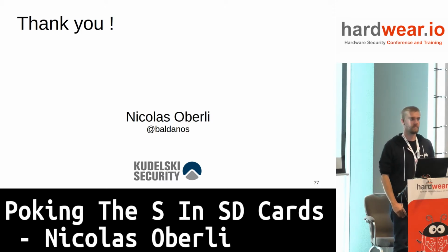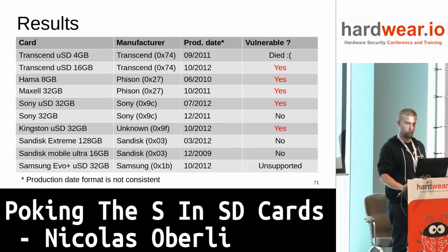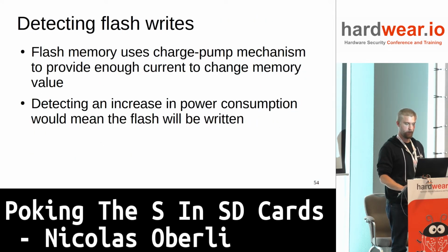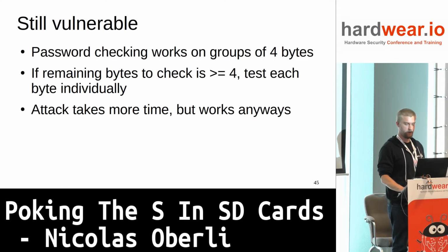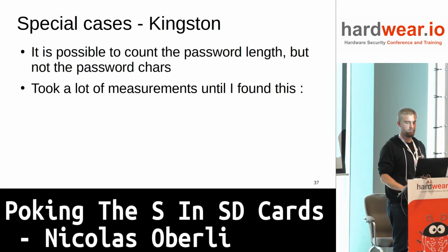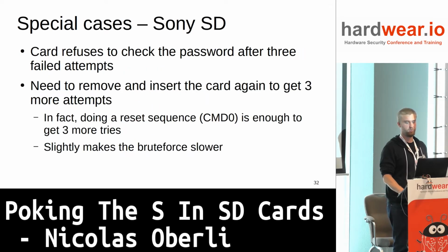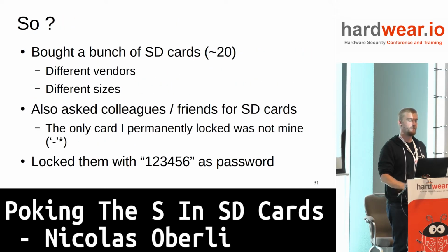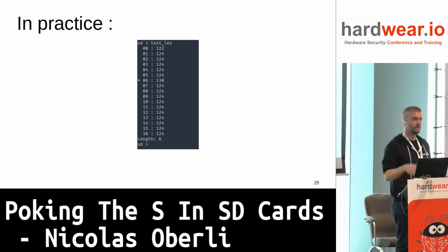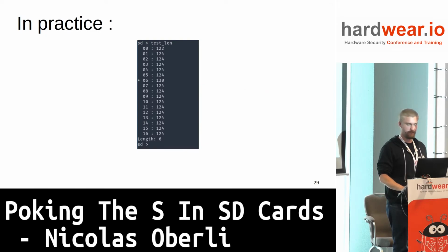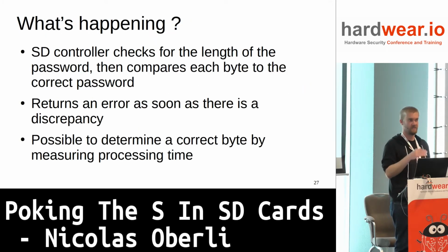So the other one, I don't remember the name, but you said you can speak SPI and also... Oh, yeah, the other protocol is SDIO. Would it be fast enough? It should, but depending on the SDIO controller you have, you might not be able to make it read dummy data like this. So it's really easy to do using SPI because it's a raw protocol. If you have an SDIO controller, you might just be able to ask it to send this specific command and get your data back. So maybe not.